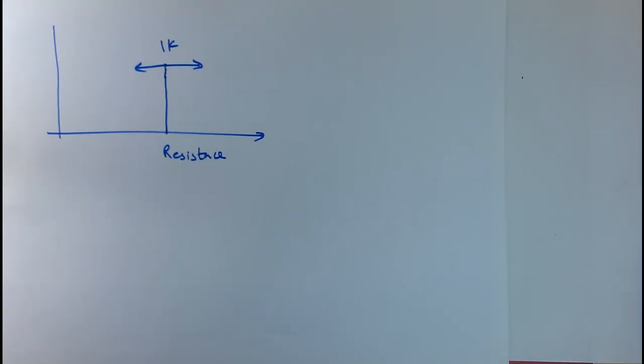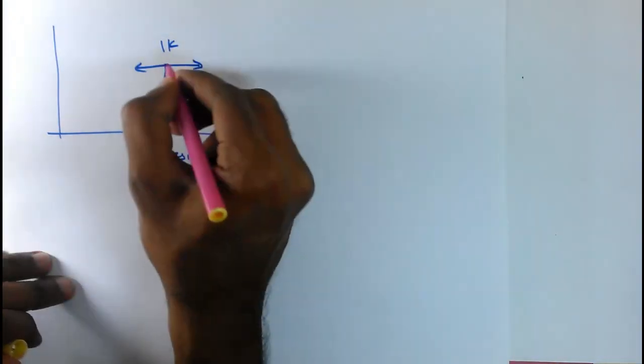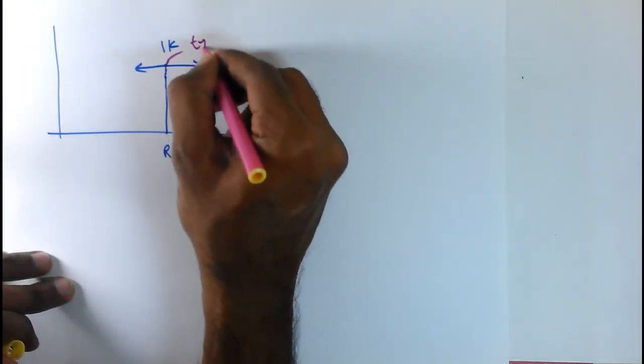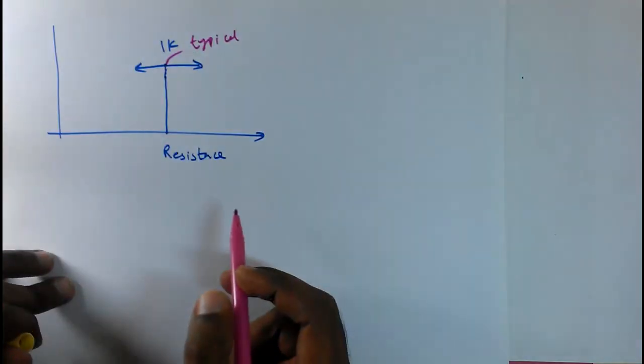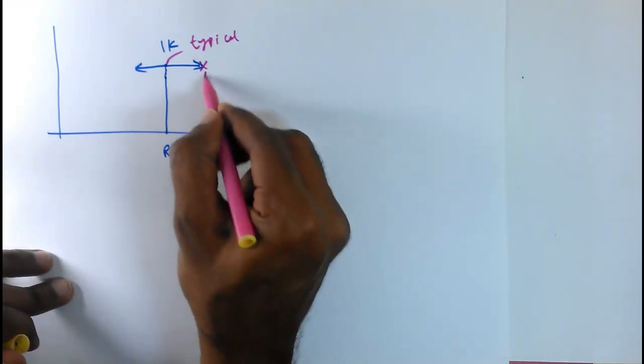Each manufacturer, that means each foundry, will model their resistance and capacitance, and they will say the maximum variation will be up to this much. That is called the process corner. So this is my typical resistance value, and this is the maximum it can go.